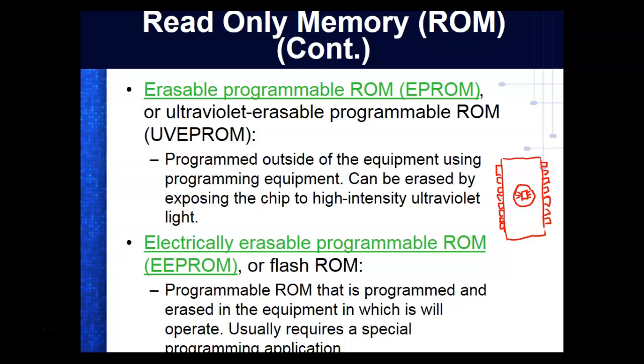So it's basically not RAM, right? You understand? Because it holds its contents. RAM loses its contents if you remove power. The problem with this is it takes longer to erase it than it does to read from it. So you ever notice when you store stuff on this thing, it takes longer to store it than to get it off of it? Because it's literally got to do what? Erase, program. When you read it, it just reads it.